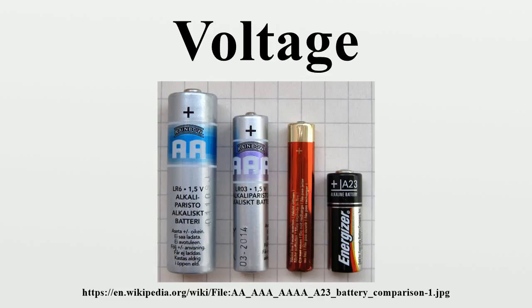Addition of voltages. The voltage between A and C is the sum of the voltage between A and B and the voltage between B and C. The various voltages in a circuit can be computed using Kirchhoff's circuit laws. When talking about alternating current, there is a difference between instantaneous voltage and average voltage. Instantaneous voltages can be added for direct current and AC, but average voltages can be meaningfully added only when they apply to signals that all have the same frequency and phase.